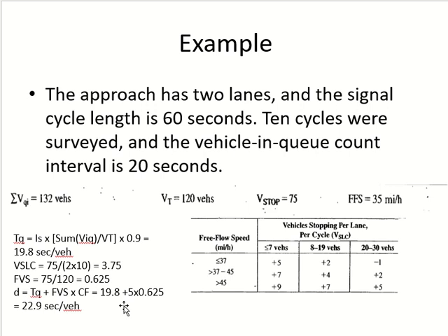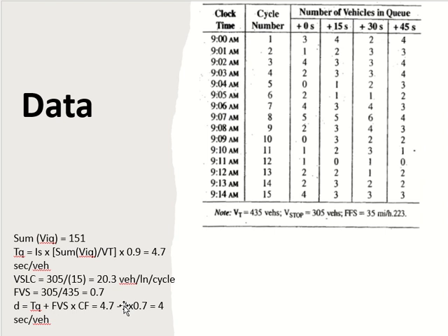So if the signal is causing a lot of vehicles to stop on a small street, that means it is basically causing the street to have a traffic jam. In that case, the total delay, not this one, this is the delay because of the signal timing, which is 4 seconds. But the vehicles are spending more time in the queue, not because of the signal timing, but because of the long queue. So it's a small street which has a very long queue.